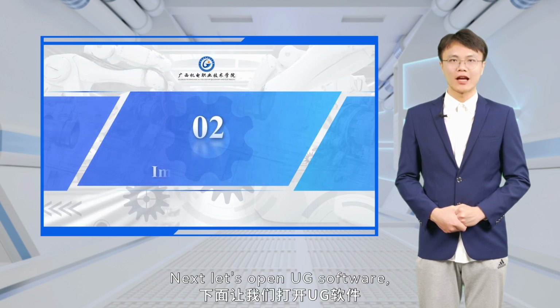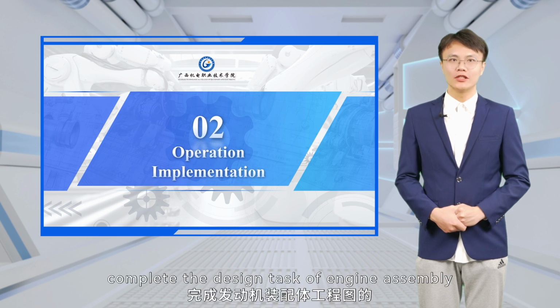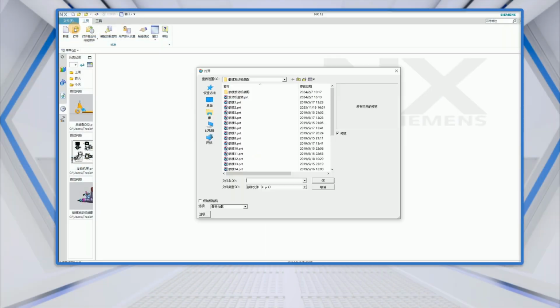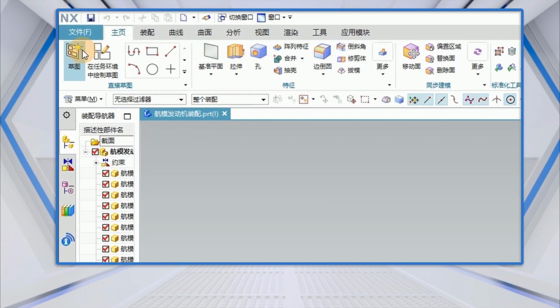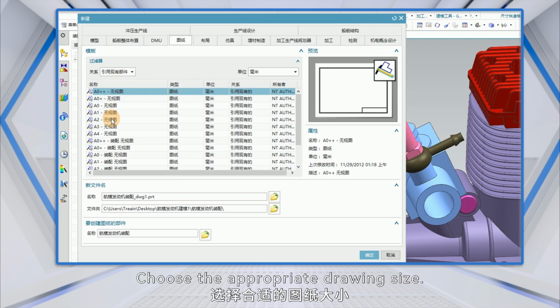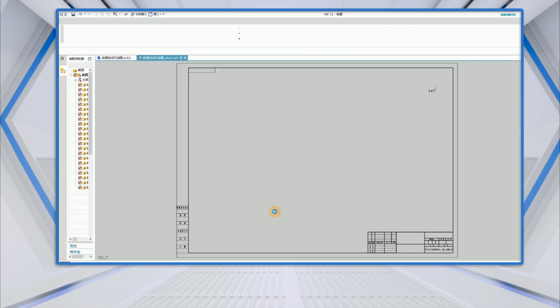Next, let's open UG software. Through hands-on practice, complete the design task of engine assembly engineering drawing. Click to open the diagram file. Click on New. Select the drawing. Reference to an existing part. Choose the appropriate drawing size. Choose A2 here. Click on OK.